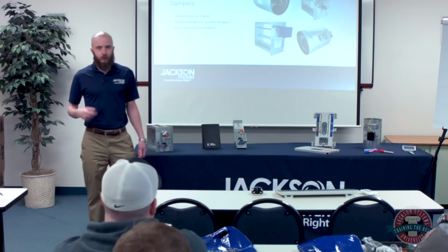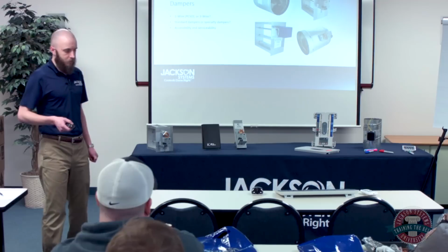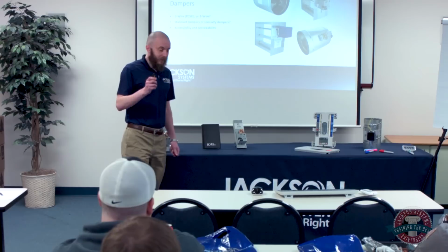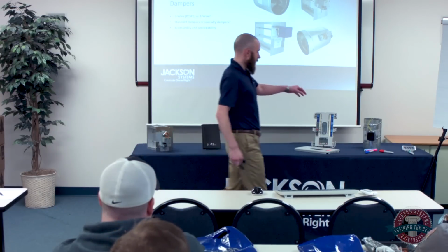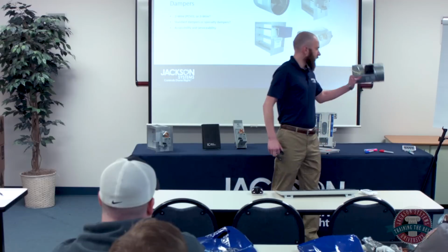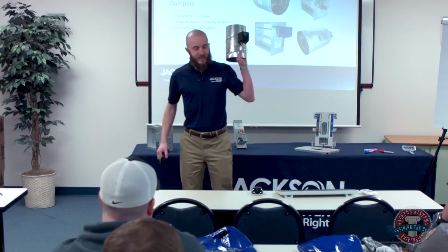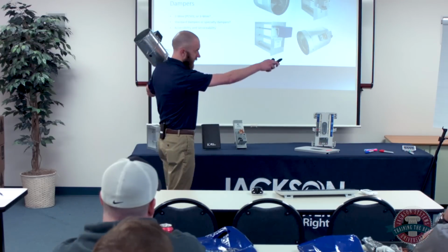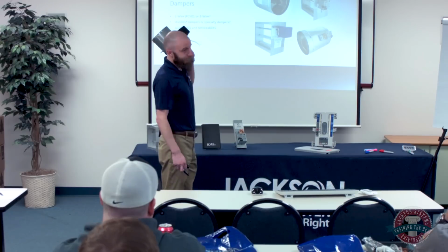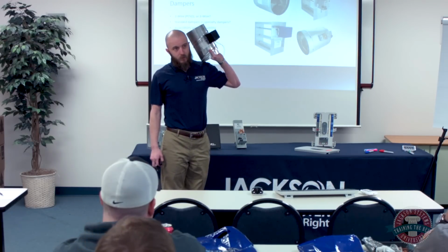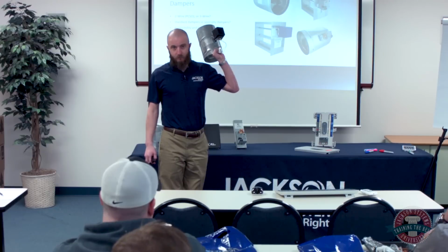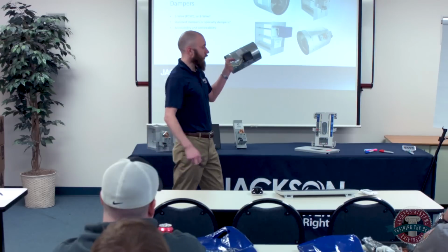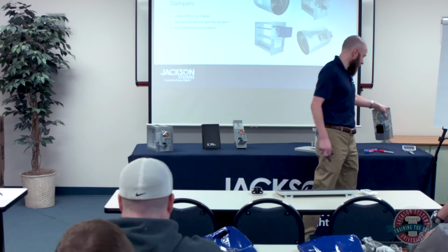Typically, people are going to install a 40 VA transformer with a zone system. And in a lot of cases, that'll be fine. But the 2-wire dampers from IO, these here, are rated at 10 VA. So these pull 10 VA each. If we were looking at this zone system over here, where we have 5 dampers, if we put 5 10 VA dampers on a 40 VA transformer, we could end up with some blown transformers. So you want to pay attention to how much VA you're putting on your system.